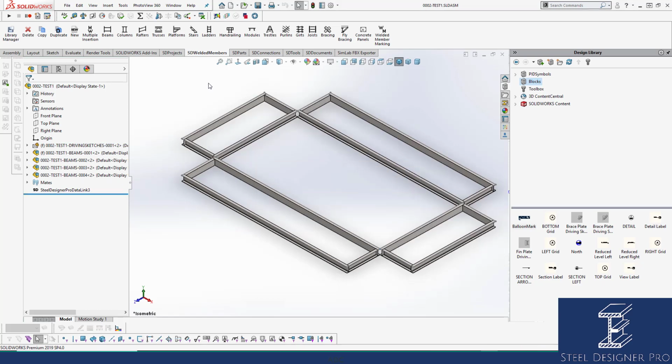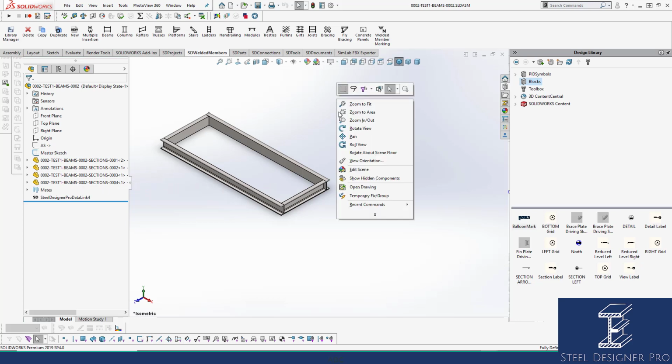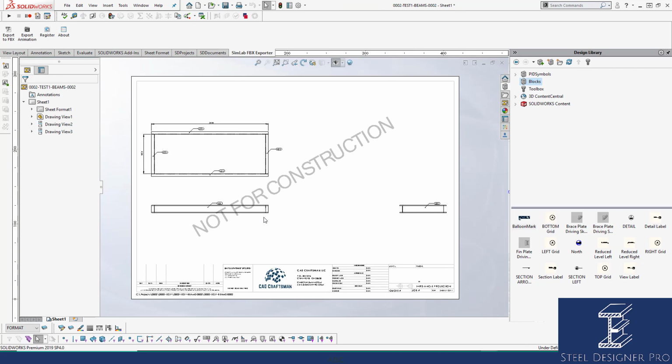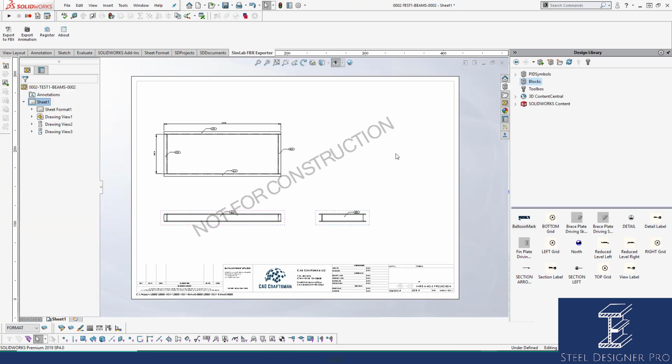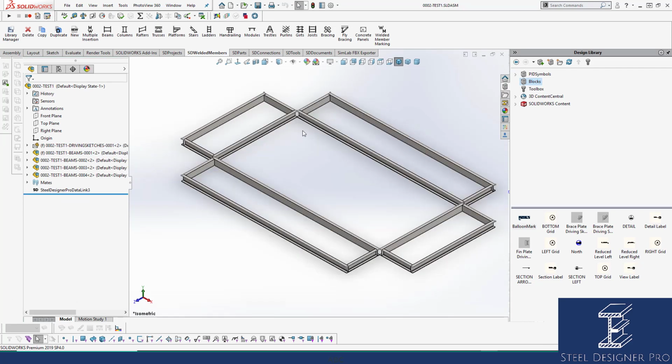However, this time I don't need to go back through each welded member's drawing and update it, because the welded member drawing was copied from this welded member to all the other welded members. And you can see the automatic filing has happened. When I go to open up this one, you'll see that they've all been given a beam 2. If I open the drawing up, you can see the drawing automatically adjusts. All I have to do is a little bit of a tidy up. Save it, get out, close off the welded member. Now I've got my 2 frames.